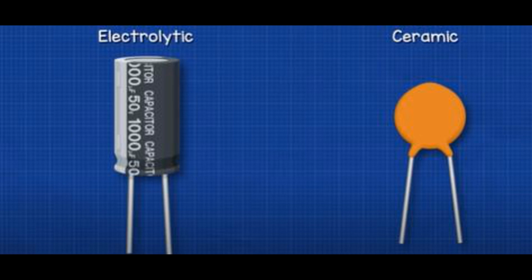Debouncing switches. Description. Capacitors are used in circuits to eliminate the noise and bouncing effects when a mechanical switch is pressed or released. Example. In microcontroller input circuits, capacitors help stabilize the signal from switches, preventing multiple false triggers caused by mechanical vibrations. Advantages of capacitors in timing circuits.